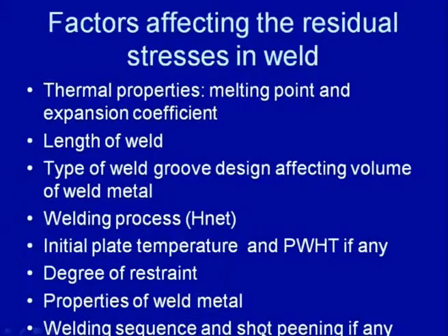Then the welding sequence and the shot peening also affect the residual stress development. Shot peening basically helps in developing compressive residual stresses by localized deformation at the surface, while the welding sequence affects the extent of expansion and contraction which will be occurring during the welding, and which in turn will affect the magnitude of the residual stresses. These factors will be elaborated in the subsequent slides also.